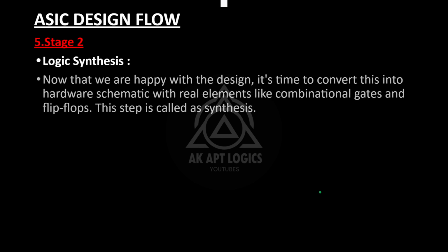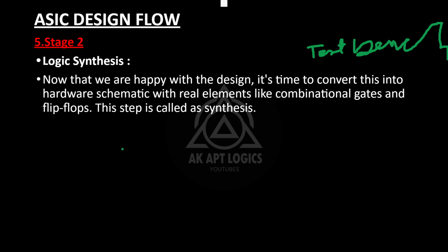So next, logical synthesis. After everything is fine, we don't need the TB. It means the TB work has been completed for the design. After our functionality is correct, the TB is just for applying inputs and checking whether the output is correct, that is, whether the design is correct or not. If the design is correct, now the design should be converted into a synthesis schematic, gate level at least.